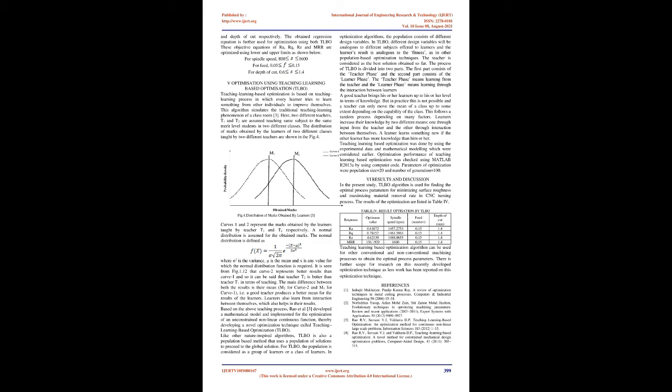For mathematical modeling, the relationship between the factors and the performance measures were modeled by quadratic regression. Regression coefficients were obtained using experimental data. Mathematical modeling refers to obtaining equations connecting response and influencing parameters. These equations are required for the optimization of the responses such as surface roughness and material removal rate. Response surface methodology-based regression equations of the four responses as a function of the input parameters, spindle speed, feed, and depth of cut, are as shown below.